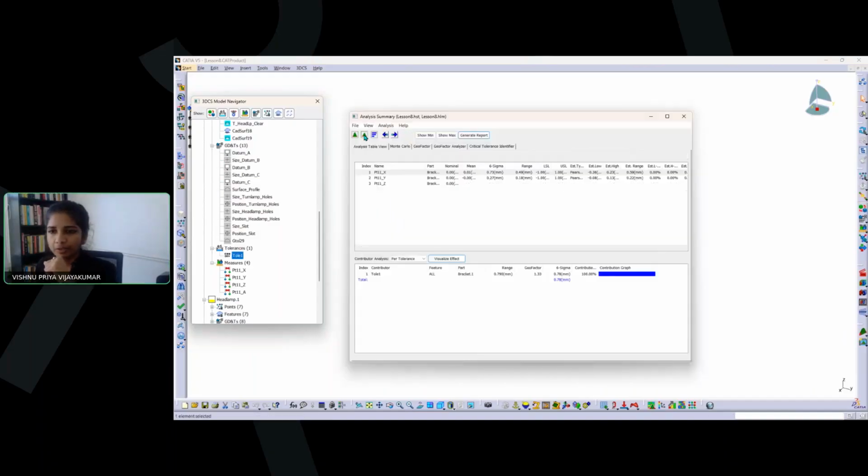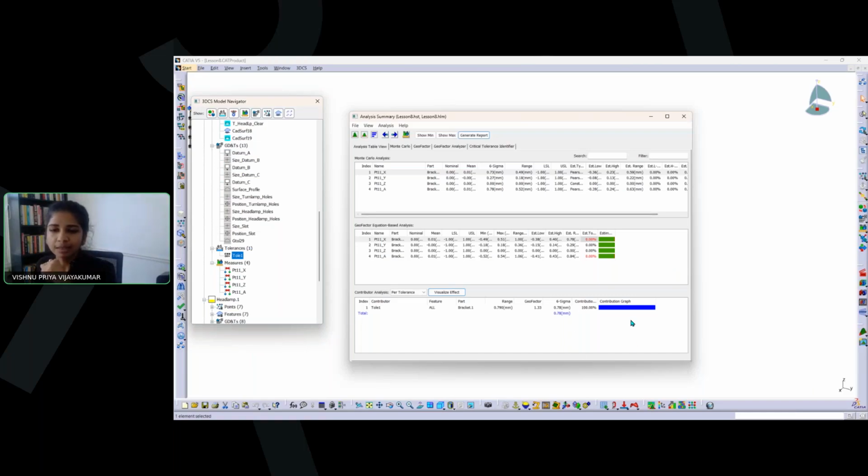let me turn on the geofactor results as well. Now you can see the Six Sigma sensitivity closer to the Six Sigma range of the Monte Carlo analysis. Whereas if I had run the traditional way, without that option turned on, it's going to match the estimated min-max range value for the sensitivity calculation. With that setting turned on, it uses the Six Sigma value and calculates based on that. So now you can see the difference in the sensitivity when it ran with the setting on.